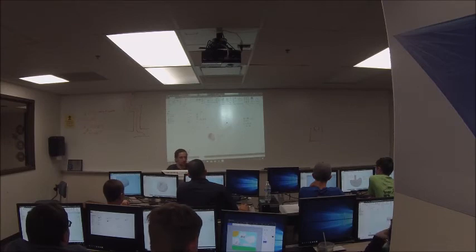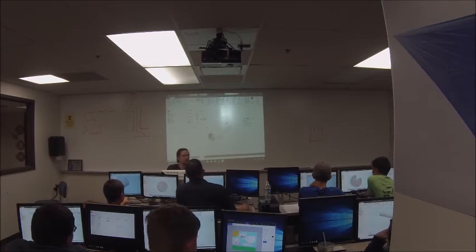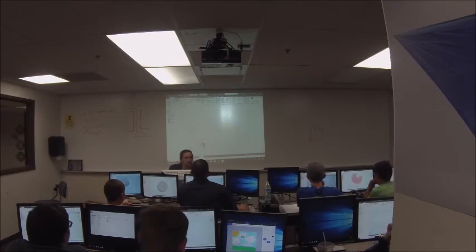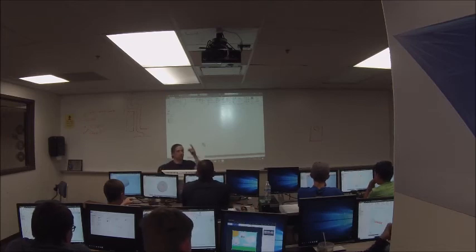Okay, you notice you can't set a distance anymore because it's going to go all the way through the part, no matter how long the part is. If I finish this sketch, I'm back to a tube. If I change the part to be 12 inches long, I still have a tube. It's still going through the whole part. So in some cases, you want something to just go all the way through. And if it's going to go all the way through your part, you should use that extents all.